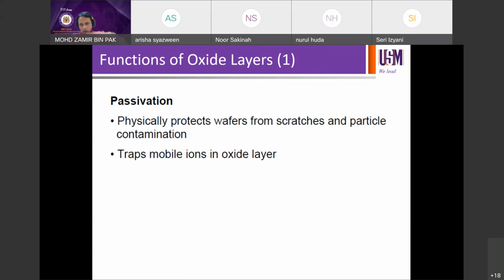Remember, we cut the silicon. So in this case, if you relate to the previous process, we grew the monocrystal ingot, and then you slice the ingot into wafers using wire sawing or diamond blade or something. Then you terminate the lattice, right? You literally terminate the lattice, you cut. So it will get damage on the surface, even though you have done the lapping process to smoothen the surface and CMP to make sure that you have a smooth surface, but there are still electronic defects, okay? Electronic defect.